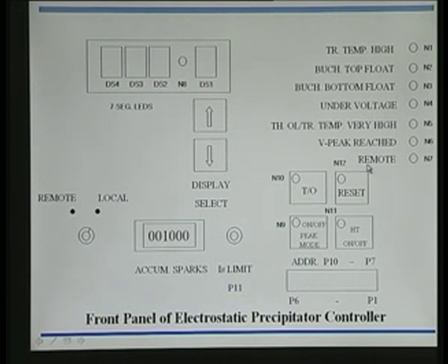You can put this controller in either a local mode or remote mode, that is indicated here, and the switch for doing that is shown here, with 2 positions. Since high voltage is involved, and the current at a particular moment may be quite high, sparking may take place. It may be as bad as lightning that you see up in the skies, and naturally that will lead to deterioration of the electrodes and eventual breakdown or burnout.